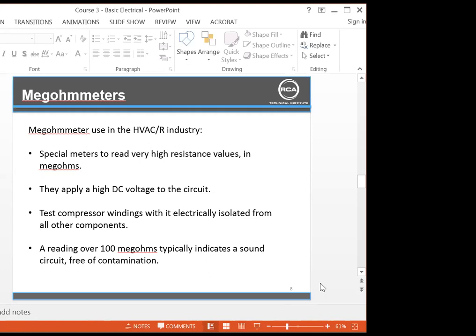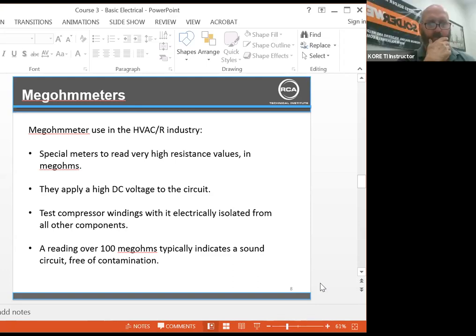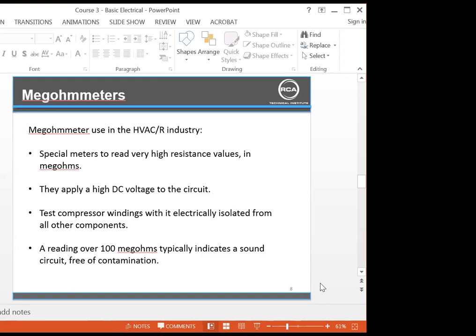Oh, absolutely. We had this bank of 4 evaporator fan motors that just kept tripping the breaker randomly, and I couldn't figure it out. I went through, ohmed out everything with my meter, and everything ohmed out good. And finally I said, you know what, I'm gonna go buy a megohm meter, and grabbed one, a Sub-Cool is the one I picked up. And started checking everything, and came across one evaporator fan motor that failed the insulation test, and replaced the motor and never went back.